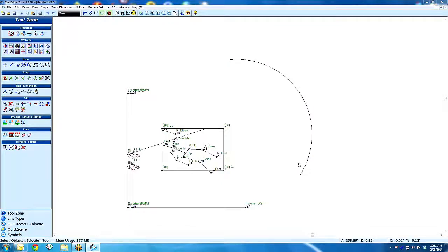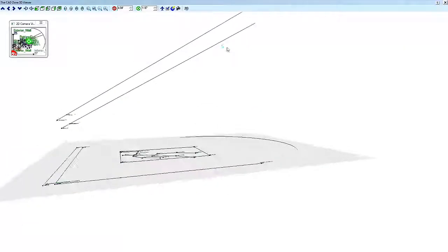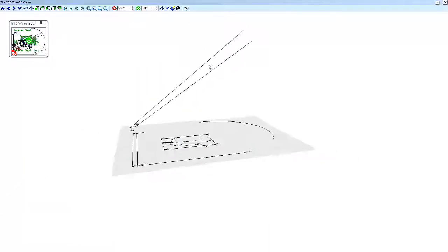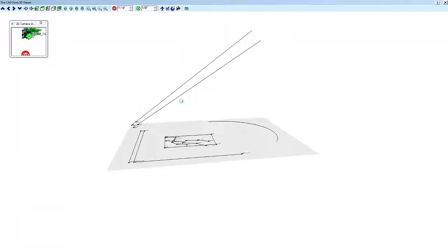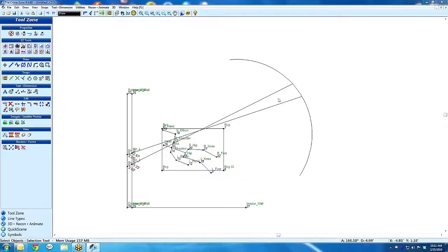Like we just want to go out, maybe out here, and we have the trim extend tool right here. Click on trim extend. Go like that. Take a quick look in 3D. So now we don't lose the slope angle of these trajectory lines, and they look pretty steep, and there's a reason for that, because it was from up in a stairwell.